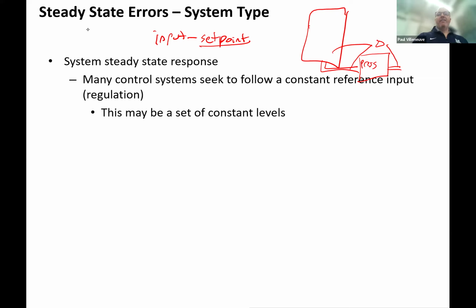So if you have a tank that is pressurized, how would you make sure that you get an accurate result? Exactly. All I have to do is zero out what the pressure of the tank is. So maybe it's 50 PSI. I feed that to this pressure. This is my reference side of things. And then I can accurately indicate what that level needs to be.